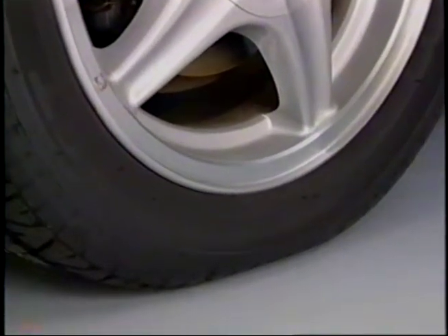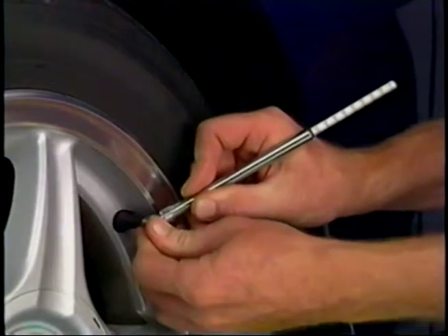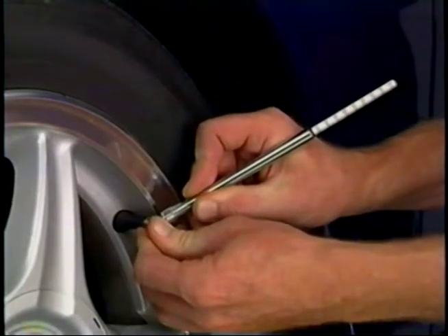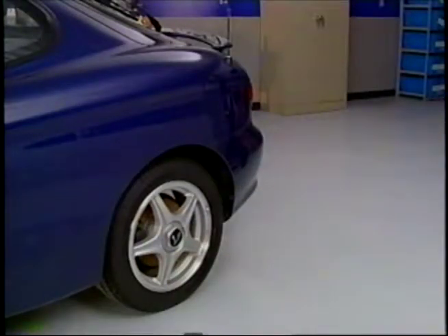Underinflated tires will also cause hard steering effort. A front tire that is overinflated will cause the vehicle to drift or pull to the opposite side and wear the tread in the center of the tire. Rear tires that are over or underinflated will cause the same wear patterns and often cause uneven braking or cause